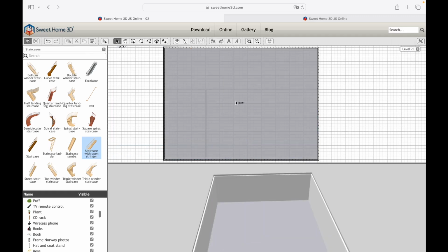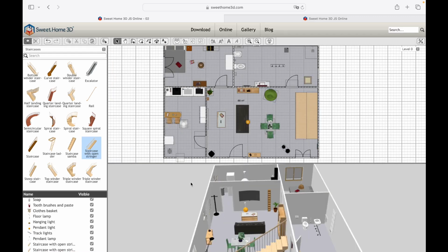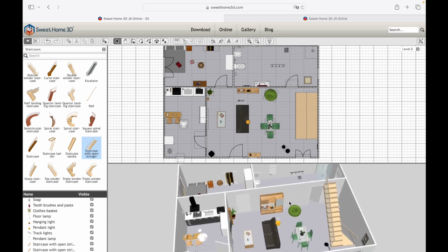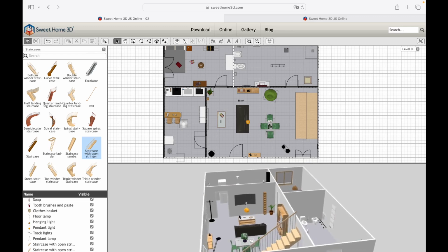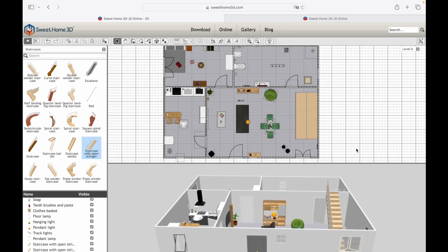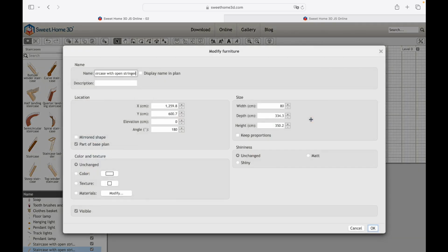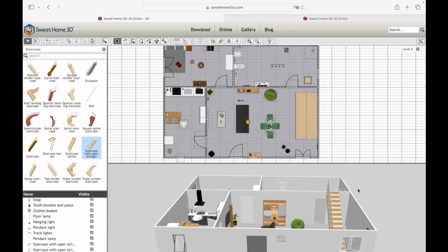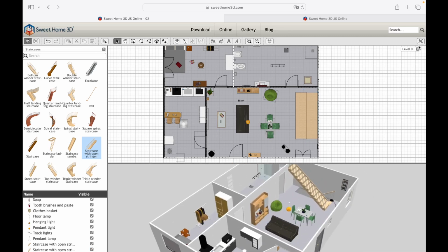With this procedure, we insert two pairs of stairs, one at the ground floor and one in the basement. I thought of inserting some classic stairs with handrails arranged in this way to allow passage up and down in this area. By clicking on the stairs with the Select Object tool, we can modify their characteristics and dimensions with the icons present, or by double-clicking and using the settings present within the window. After inserting them, we can continue our project by furnishing the new areas of the house.